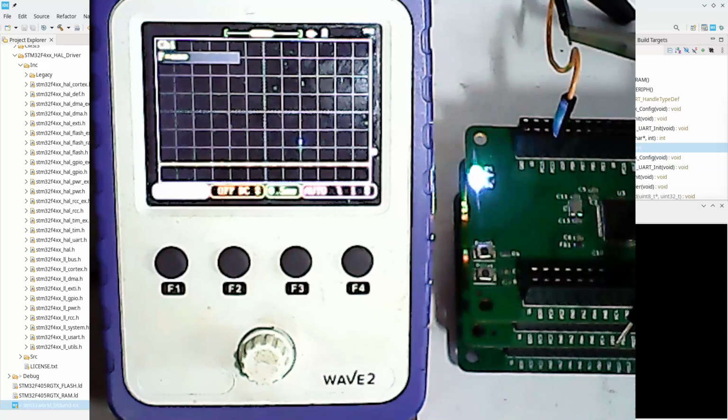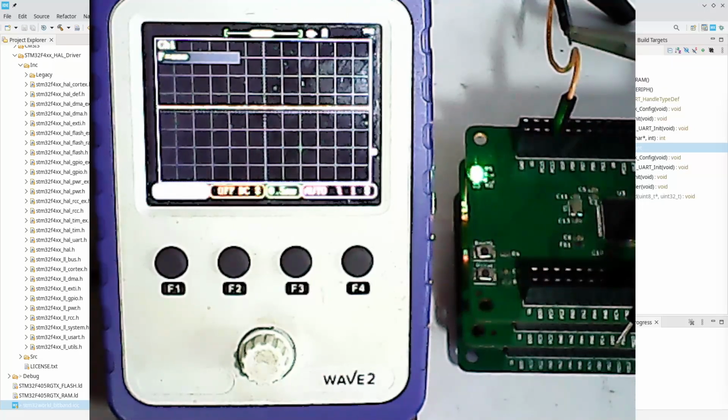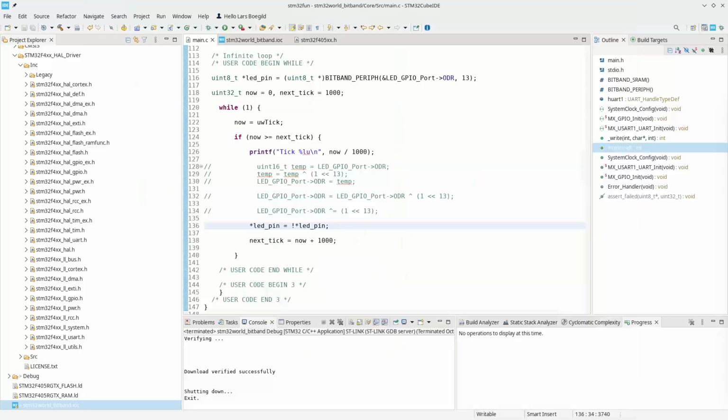bit, only that bit. Now the beauty of this is, no matter where an interrupt happens, this line of code here, oh sorry, I forgot to remove this. This line of code will not touch any of the other bits. If the other bits are being modified by an interrupt or whatever, or a timer, it doesn't matter. This will only toggle that one bit in one port. Now, this can be used to do all kinds of things if we want bit manipulation.